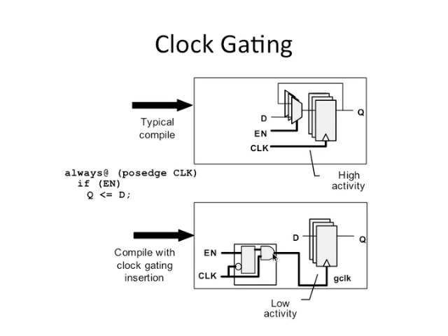And so here you see what we are doing. We are putting an AND gate in series with the clock path. So we have to be careful in how we control the other input of the AND gate. When the clock is high, we don't want the other input of the AND gate to go up and down, right? Because then the output of the AND gate will also go up and down, and then we have too many edges which can mess up the system.